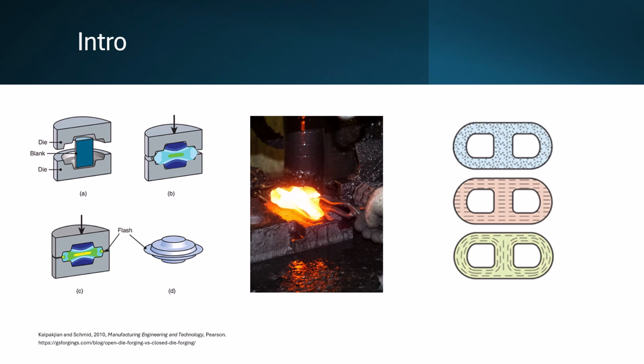We will start with an overview of the forging process. Forging is a process of shaping a hot or cold metal, although we will not be discussing cold forging today. In hot forging, even though the temperature is elevated, the material is not melted. Instead, solid stock material is subjected to forces that deform the material repeatedly until it is in the desired form. These forces can be applied to simple open dies or more complex closed dies, which we will focus on today.